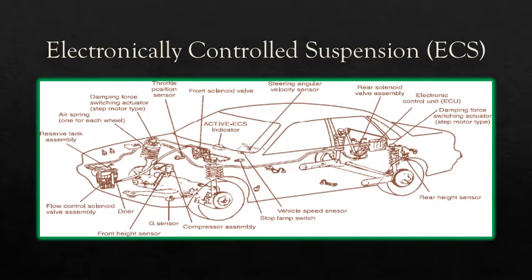Similar inputs are analyzed when the car is being sharply accelerated, except that the override factor is throttle position, not brake application. In this case, adjustments are made to the car's rear suspension to keep the back up. As a front wheel drive car dips at the rear, the front wheels change their angle of contact with the road. If this changes too quickly, the front driving wheel can lose traction. The sensors which monitor rear suspension also check on the load the car is carrying and keep the rear up.